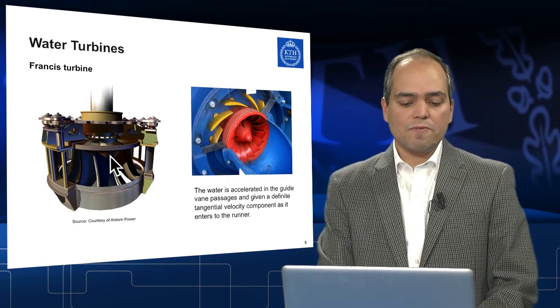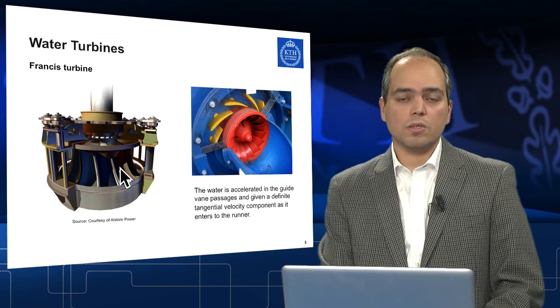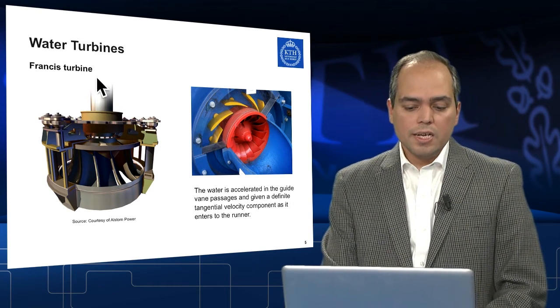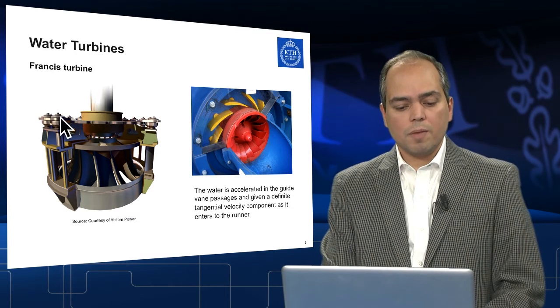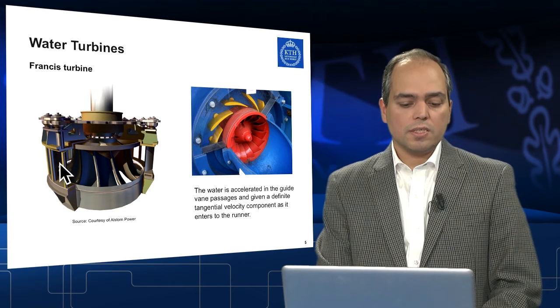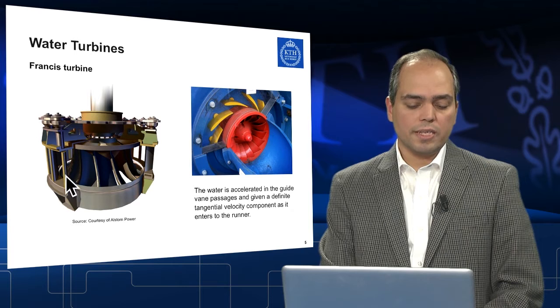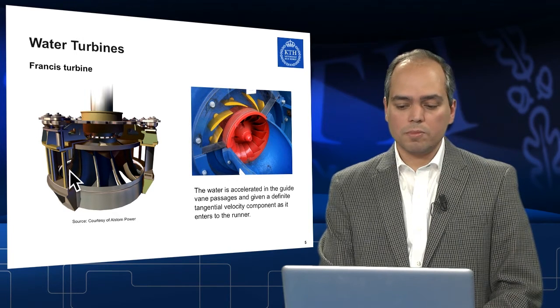So it's in fact the blades. Normally they are between 12 to 24 blades inside the runner, depending on the design. You could see the guide vane mechanism here, and this mechanism on the top makes it possible to adjust the guide vanes' opening. So in fact, each guide vane here could rotate along its axis, and then this opening is adjustable.